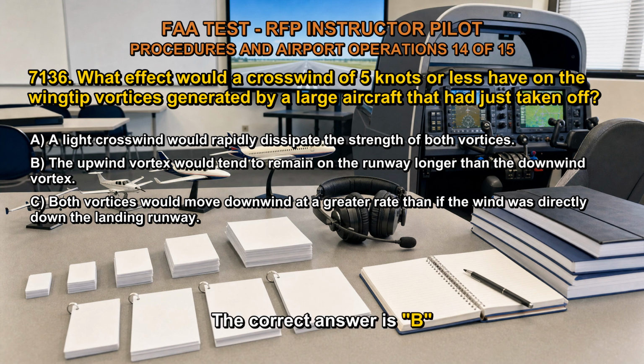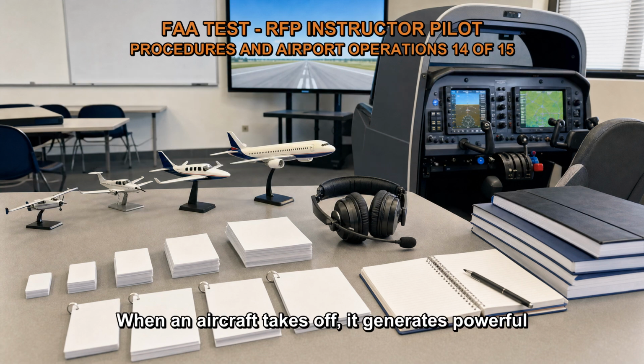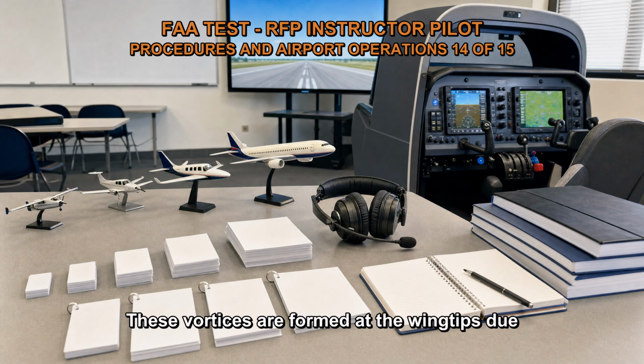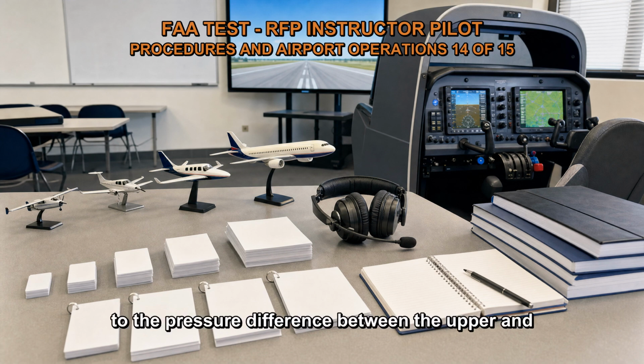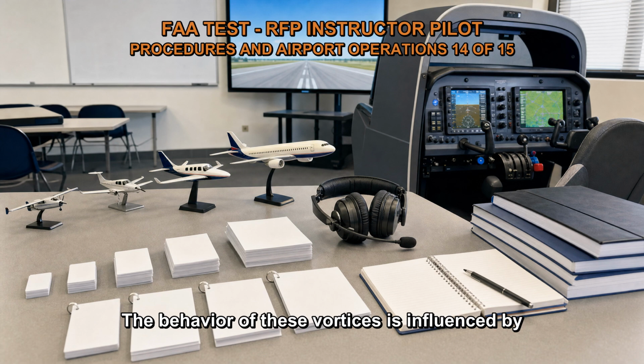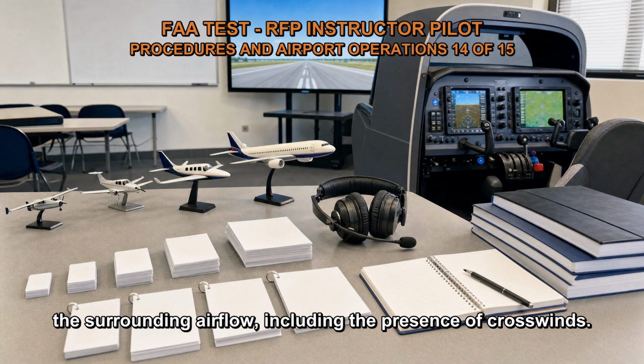The correct answer is B. When an aircraft takes off, it generates powerful vortices of air called wingtip vortices. These vortices are formed at the wingtips due to the pressure difference between the upper and lower surfaces of the wings. The behavior of these vortices is influenced by the surrounding airflow, including the presence of crosswinds.